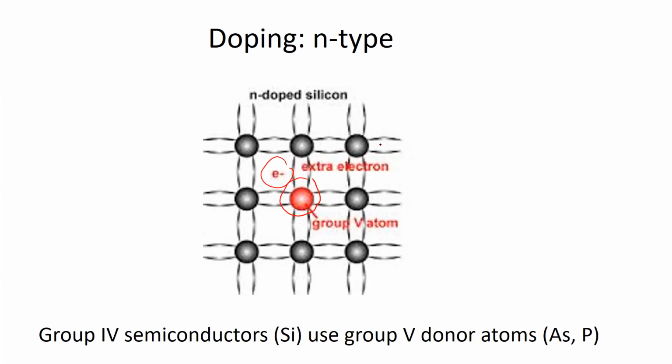So sometimes we work out the donor concentration. But secondly, because the atoms have lost one of their electrons, they no longer have an equal number of electrons and protons. And that means that overall, this arsenic ion, this group 5 atom, has a positive charge associated with it now.